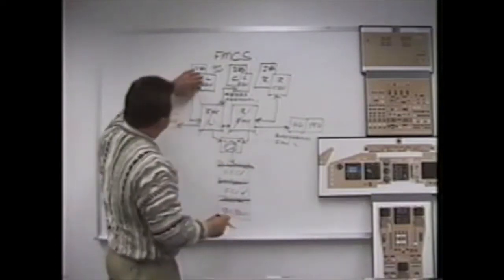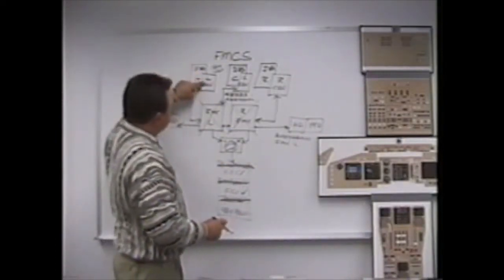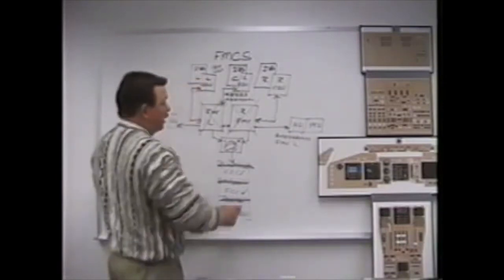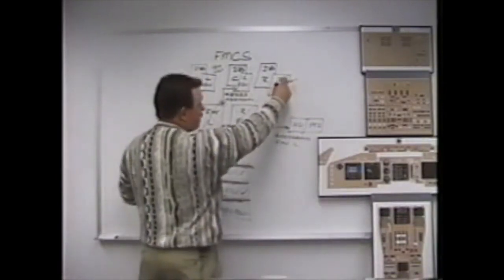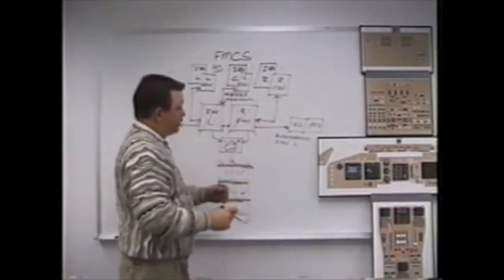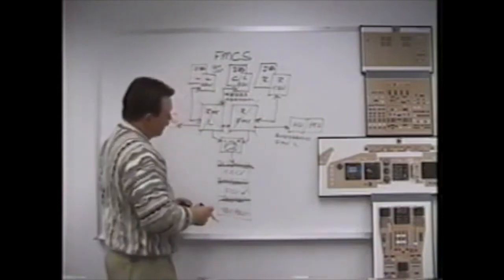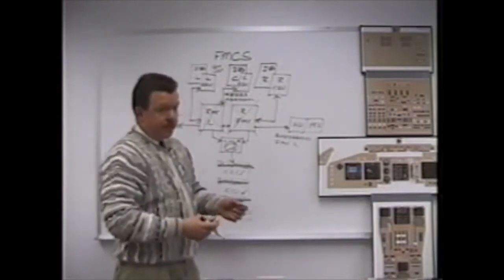In fact, you will manually tune the left VOR, the left ADF, and the left ILS on the left CDU. You'll tune the right radios, VOR, ADF, and ILS on the right CDU. You need to go to the center CDU and tune the center ILS if you expect the center autopilot to fly the approach. Can you do a Category 2 approach in this case?